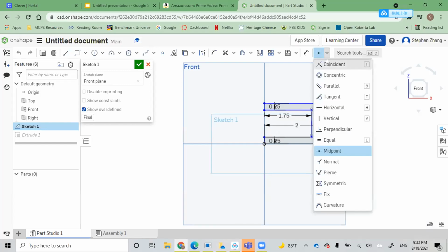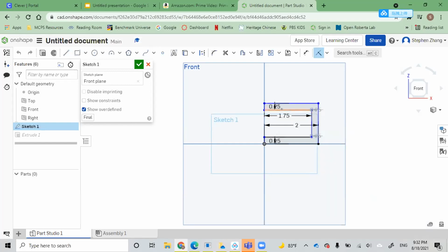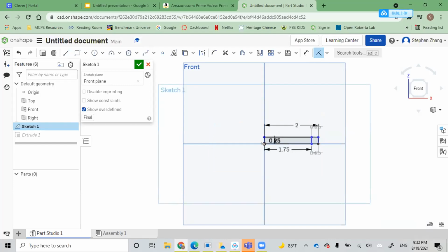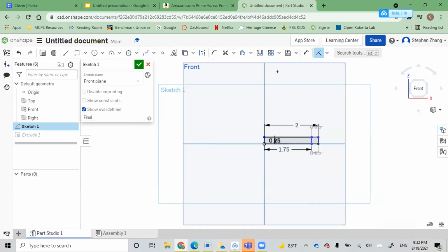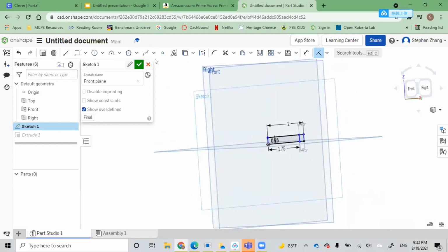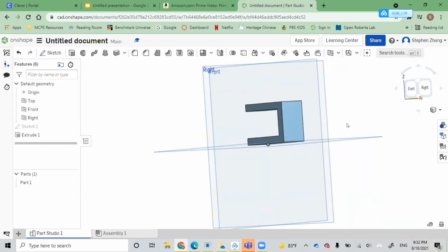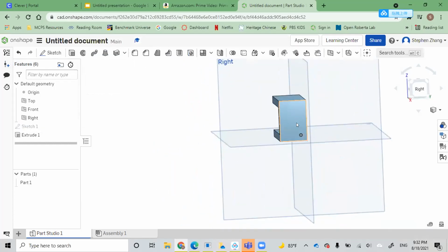Oh, so unfortunately, that's probably not going to happen because you have these lines that have that point as endpoints. So that constraint isn't going to work the way that I think you want it to. I guess the upside is you don't really need that to be in the center. But like I can't get the circle to be on the center of like here, can I? You can, and you can do it the same way that we did that slider in the ellipse trammel in CAD 1.